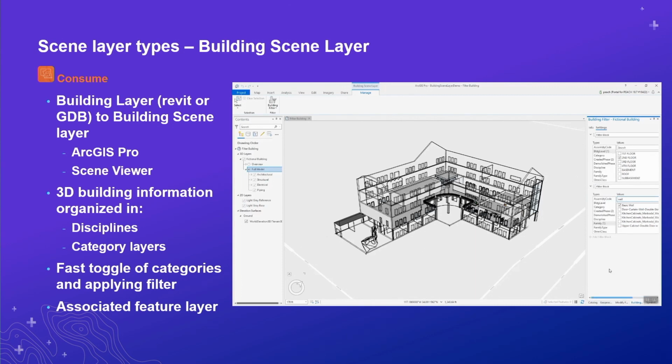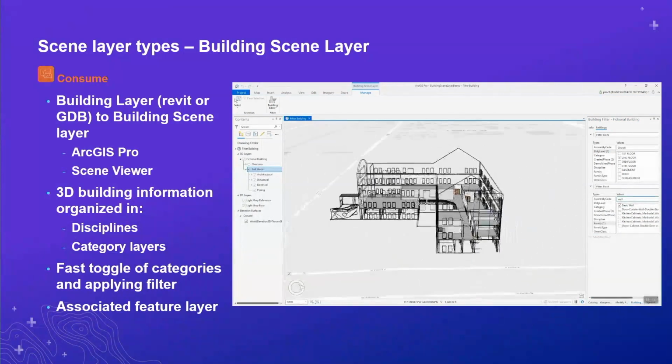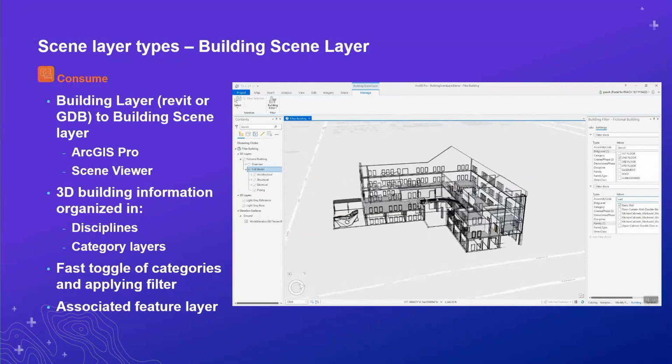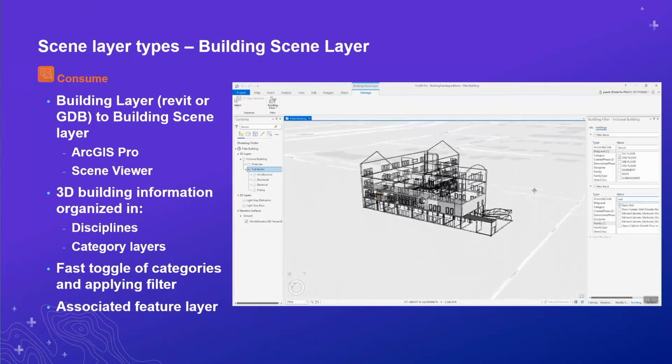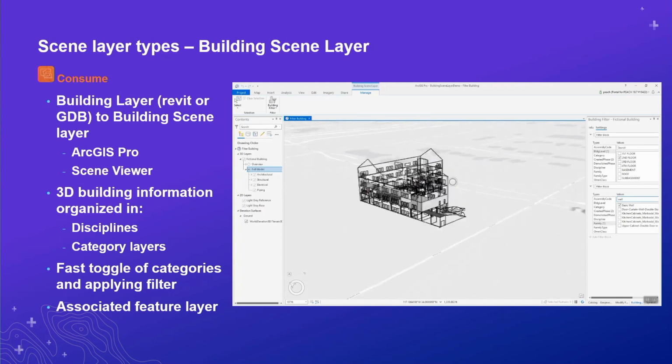I can now see the outer wall in addition. So I can easily just, with a couple of clicks, create a complex query and visualize it by combining different drawing modes. The order of the drawing modes are important. The filter block on the top gets priority.